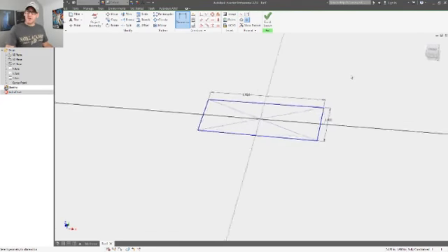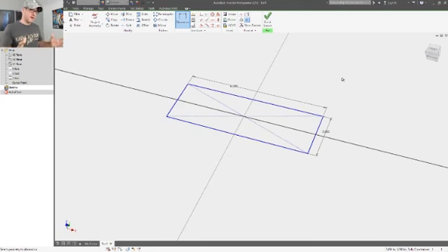And we can start to use parameters right away inside of Inventor. So if I know that this 2 inches is always 1/3 of the overall length, rather than typing in 2 inches, I can actually highlight that parameter, and you're going to see it says D0.